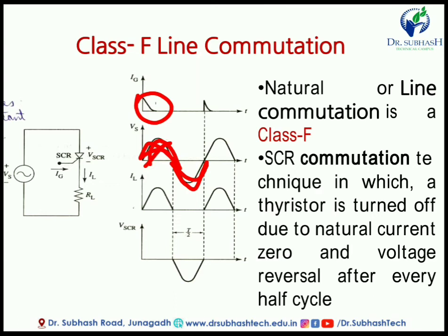Whenever we give a pulse to the SCR, the SCR becomes on. Here you have set the firing angle to 0, which means whenever this waveform starts, at that time we give a pulse, so the SCR stays on through this positive half cycle. But whenever our waveform cuts the origin line, the voltage or current goes from positive to negative, which means it reaches the 0 level.